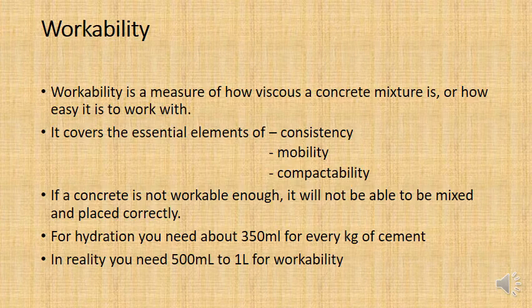They're both liquids, but in terms of their thickness and ease of moving, that's basically what we mean when we are referring to workability. And so it's basically a combination of how consistent the concrete is, how mobile the concrete is, and how easy it is to compact the concrete.